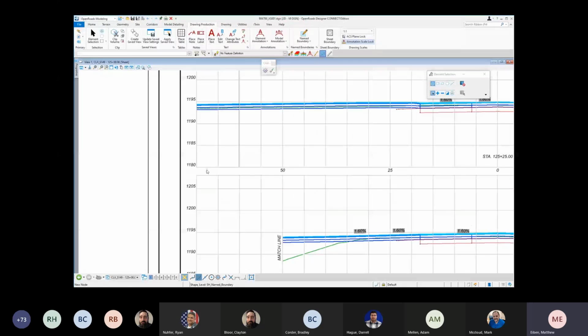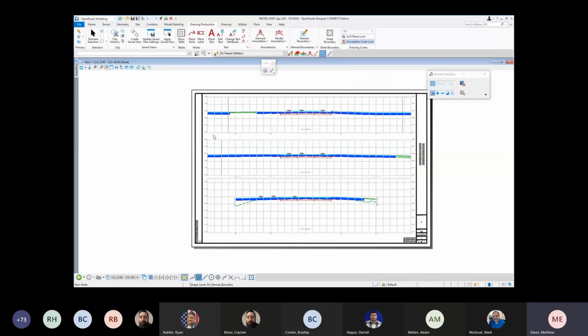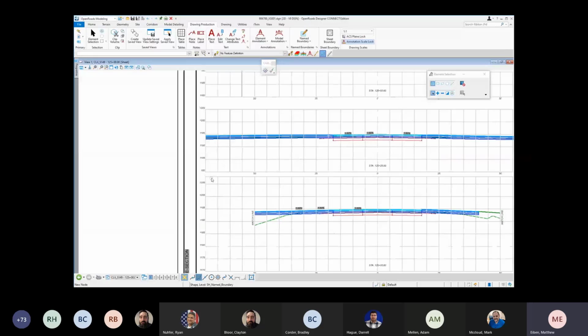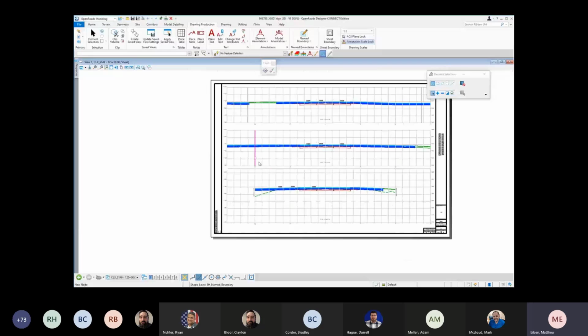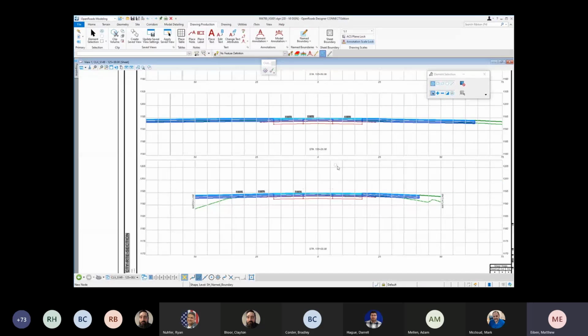that boundary is also changed and moved, but you'll notice the difference, or the distance between the two grids has changed. So you'll want to keep that in mind, that if you adjust that too high, you may end up with overlapping cross sections on your view. But again, if you needed additional annotations, or maybe you needed to add some depth to your section to get some existing utilities in, that could be one way to modify the view there, or adjust that name boundary so you can get the correct clipping to show the section appropriately.